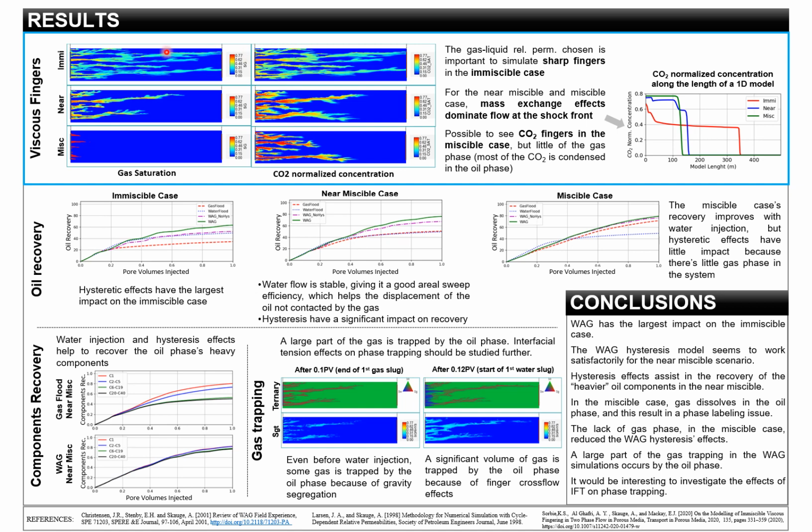For the immiscible scenario, we can see a very similar profile, and that's what we expected, of course. The gas is mostly pure CO2. And we also see that the gas-liquid relative permeabilities that we use do produce sharp fingers in our model.